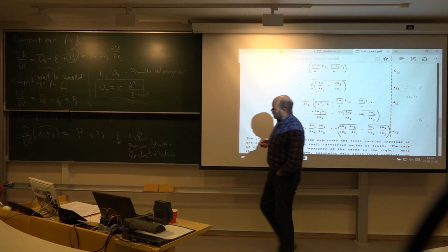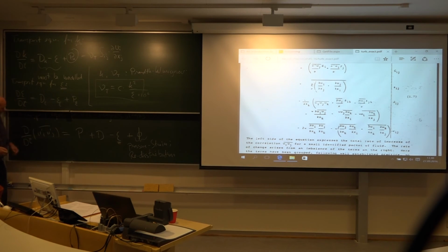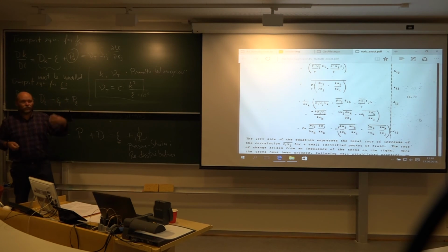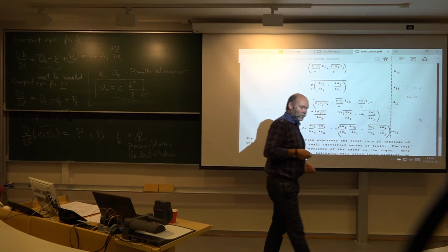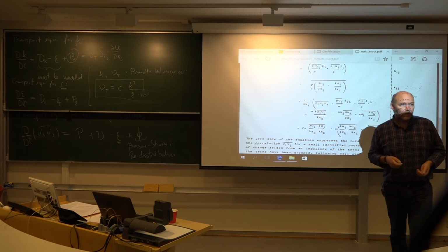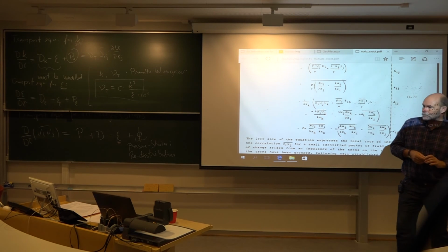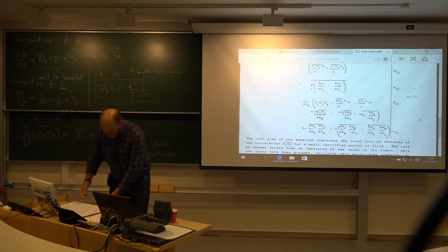And now also, what's the price? For a full Reynolds stress model, you need 6 transport equations for these Reynolds stresses, plus 1 transport equation for the dissipation, plus you have already had 3 transport equations in the Navier-Stokes, 1 for each velocity component. So a total of 10 transport equations. This is getting expensive when it comes to CPU. But it covers more physics, absolutely. So this is what we call a full Reynolds stress model.